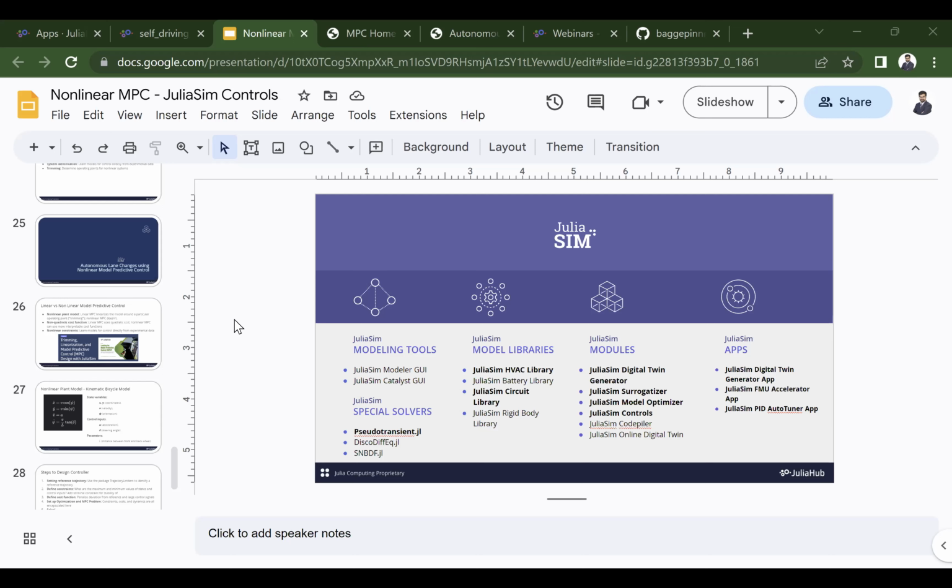So what you can do is, once you have a model, you can then use our model discovery workflows and pipeline to add physics and extra terms to your model. So that's the system identification step. Once you run it through model discovery, you can then get a new model, which is a combination of these data-driven terms in the model. And now that you have this data-augmented model, you could then wrap a controller around it, into MPC and all of that. So yes, you absolutely can do that. That is definitely possible.